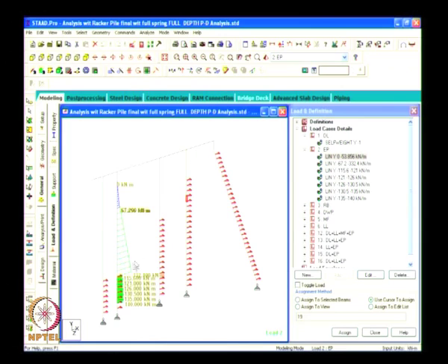When the soil is sliding here, if the diaphragm wall is not there, the soil will collapse. Since the diaphragm wall is there, when the soil is sliding, the weight of the soil will exert some pressure on the diaphragm wall, that is called active earth pressure. Active earth pressure means when the wall moves away from the soil. Because of the sliding of the soil this diaphragm wall will move, this movement is away from the soil, that is called active earth pressure. There is a procedure to calculate, so that active earth pressure is shown here. Next.